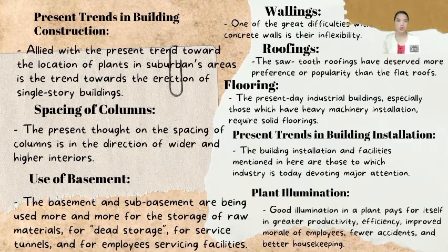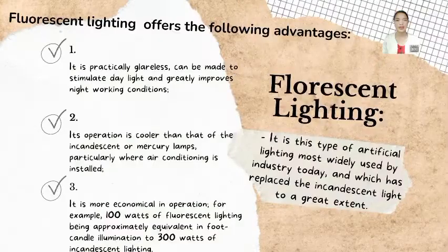Lighting fixtures should be appropriate to the type of work that they are to illuminate. A display of merchandise to make it look attractive calls for a special combination of fixtures which should not be used anywhere else in the establishment. In factories, the illumination should be so planned as to give the workers adequate but not over-illumination at the spot where they are working. The objective in factory lighting is to enable the worker to see what he is doing without hesitation or strain.